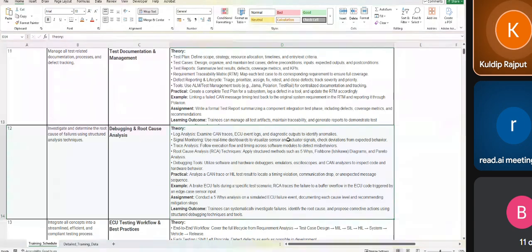But of course, if you want to take another controller, for example powertrain or any other controller as part of a subsystem, we definitely have scope to incorporate it in our HIL system. And in future, we will be able to put in a DBC file from the old project that we have prepared. We are trying that also. With the HIL system that we have just seen, you will be able to import a DBC file into it, and we can see those messages in real time.